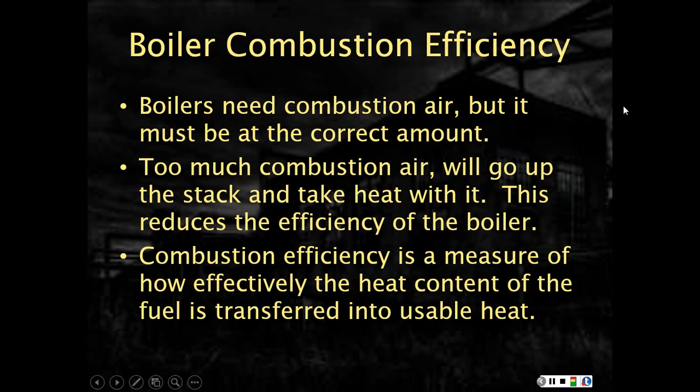So boilers need combustion air, but it must be the correct amount. If we have too much combustion air, the excess air will go up the stack and take heat with it. This reduces the overall efficiency of the boiler, specifically the combustion efficiency in this case. Combustion efficiency is a measure of how effectively the heat content of the fuel is transferred into usable heat by the boiler or furnace itself.